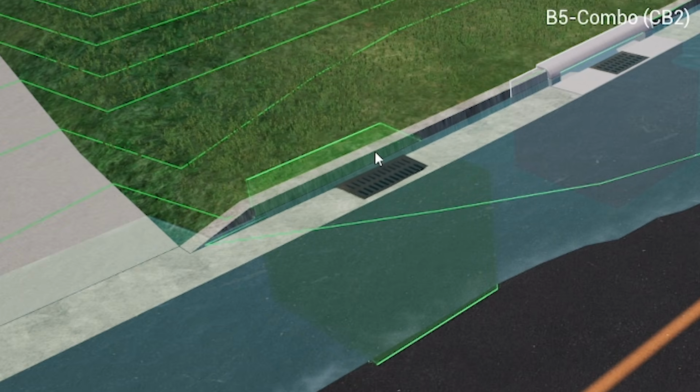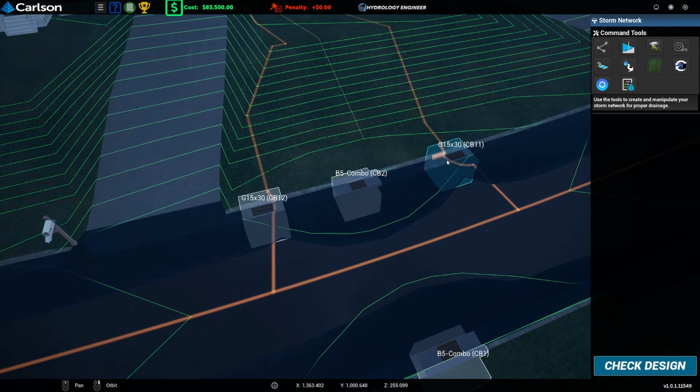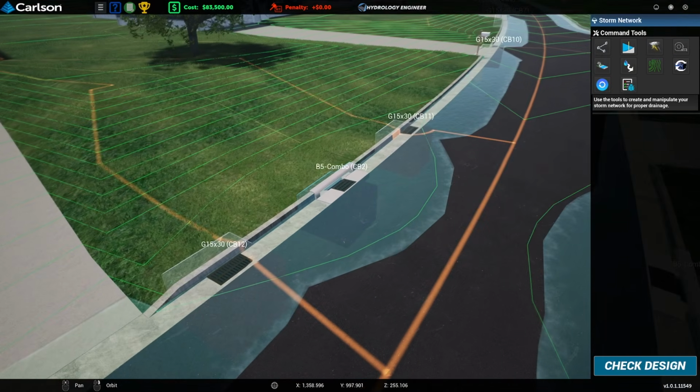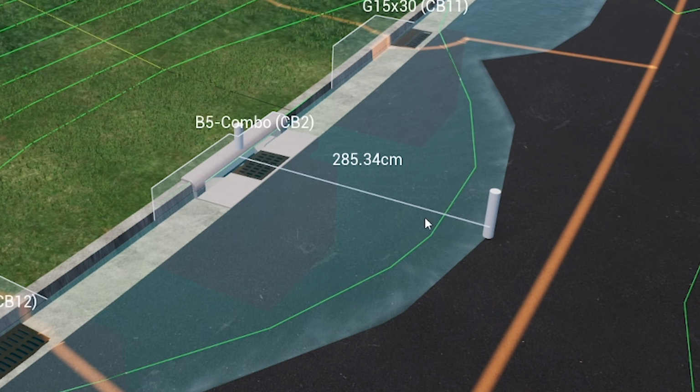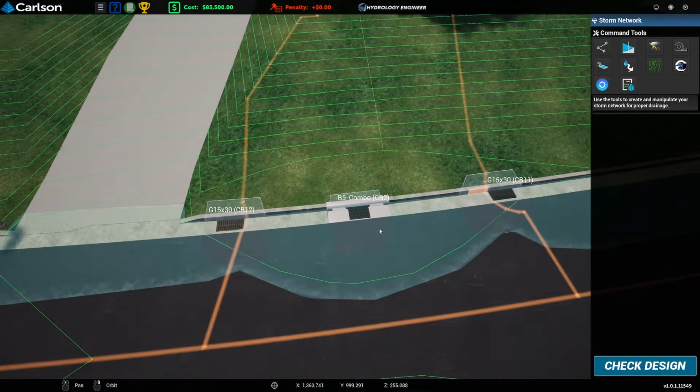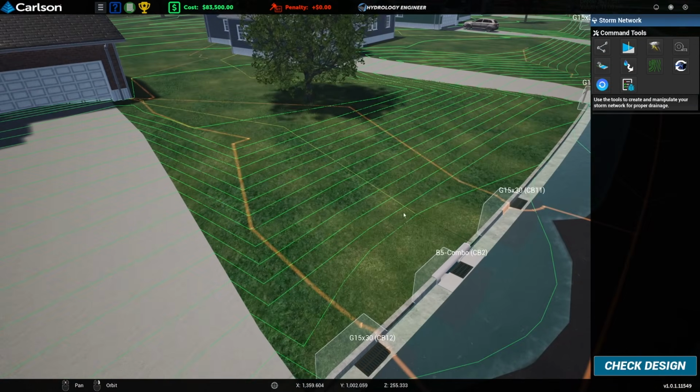I think 2.4 appeared about there-ish. So now with gullies either side of that. Oh no, it's still not good. That goes up to 2. Blooming out. Okay, so I think this is flooding because we got such a large amount of water contributing